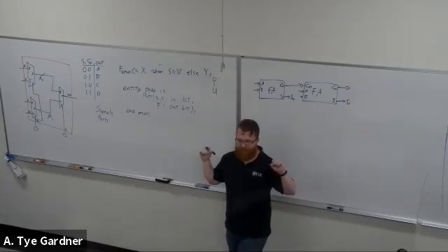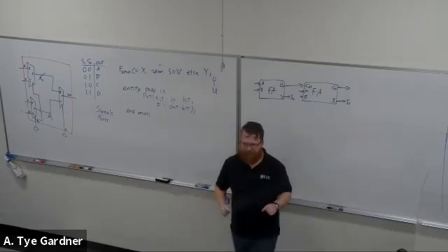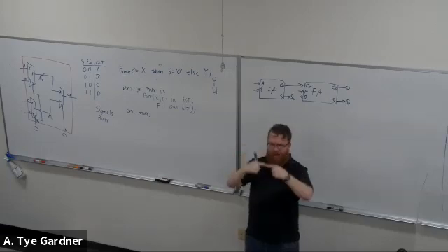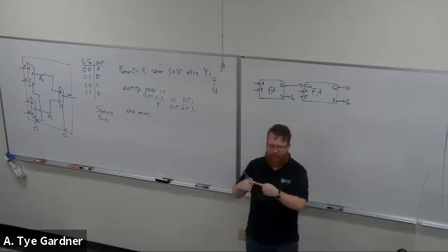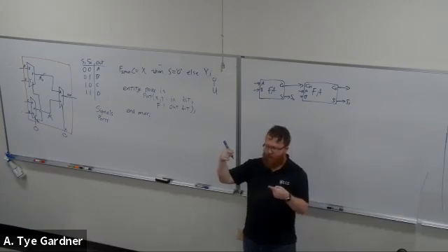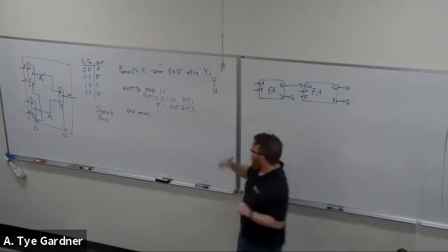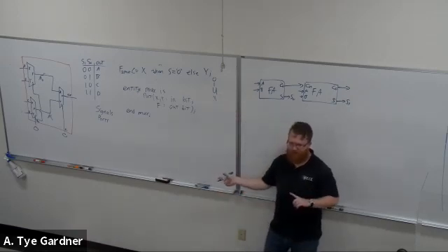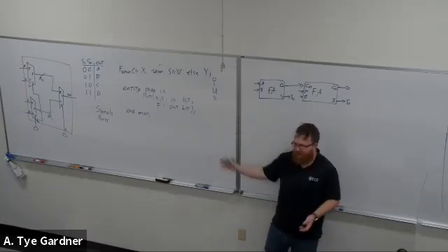I don't know. What if I did one of the other mistakes I've seen you guys make where I have two AND gates and I plug them in together? Well, that output is what we call dual driven because one of them could be trying to make it 0 and one of them is trying to make it a 1, right? In the case of your NAND gates, the 1 is stronger than the 0, so it always is 1. In reality, sometimes they're perfectly matched. We would call that X because we don't know, right? We've used X before as don't cares. This is really we don't know, okay?